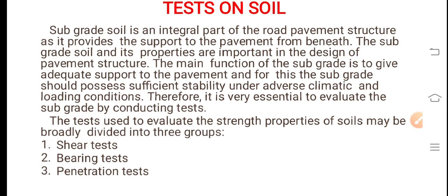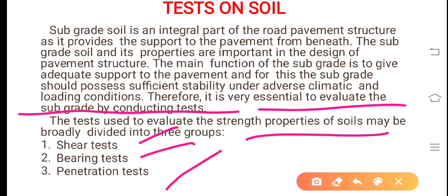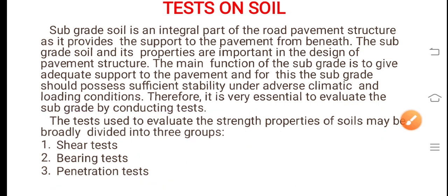Therefore, it is very essential to evaluate the subgrade by conducting tests. The various tests used to evaluate the strength properties of soils may be divided into shear test, bearing test, and penetration test. Shear tests you have already conducted in geotechnical engineering: direct shear test, triaxial shear test, vane shear test, etc. Bearing test: plate load test. Penetration test is one of the tests which is conducted, the CBR test.